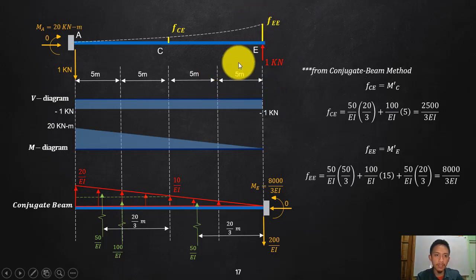Vertical force only is 1, so that is the same but in a different direction. Horizontal is no force, so 0. This will give us a moment about A to be counterclockwise, 1 times 20 is 20, the distance being 20. And then counteract that with clockwise, which is 20 kilonewton meter also. Draw the shear and moment diagram. So negative, that is all throughout, and then that will be zeroed by this positive 1. And then the original positive 20 kilonewton meter, and then of course this moment here, since there is no moment along, so that's the only moment here, which is a negative 1 times 20 that will give us negative 20.